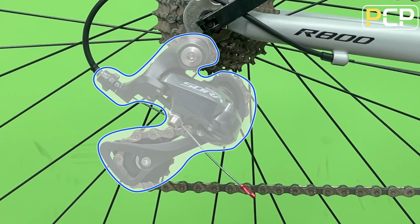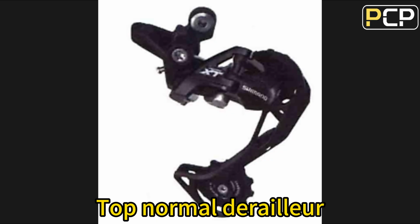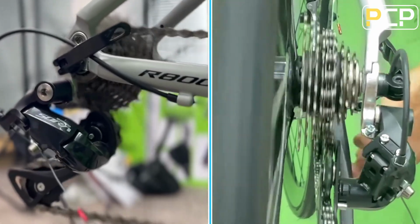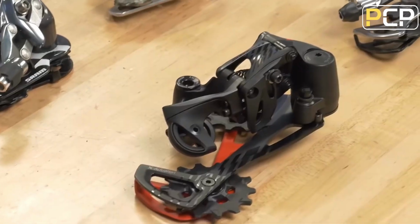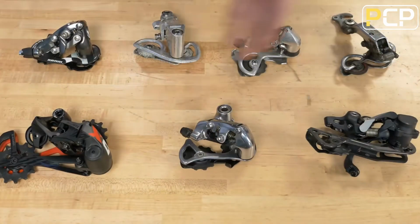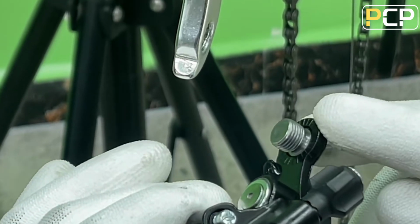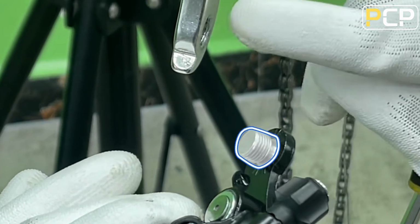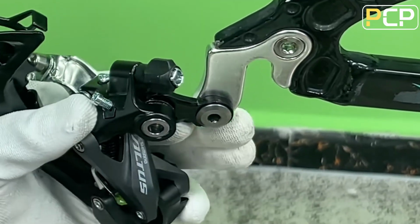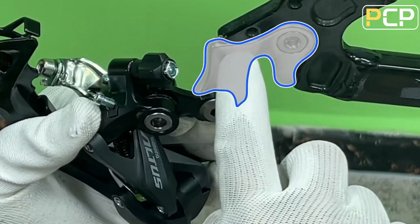The rear derailleur is mainly divided into external derailleur and internal derailleur. According to the wire pull direction, the external derailleurs are divided into top normal and low normal types. Based on the length of the guide wheel bracket, they are long, middle, and short types. The advantage of the short derailleur is that it can better avoid hitting obstacles. The middle and long types can use a flywheel with a larger number of gear teeth.